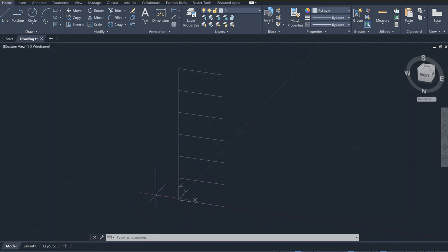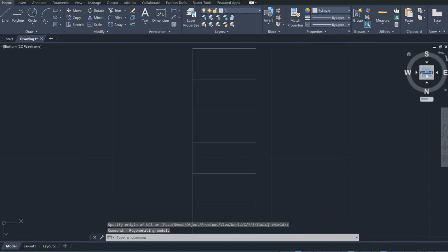That UCS actually is controlled by the UCS command. So basically you type UCS, enter, enter, okay? That takes you to the original XYZ plane. When you type UCS, enter, enter, it gets you right there, okay? And I'm going to click on the front view.